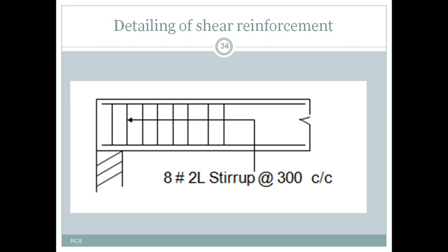We have started the design steps. We have the following design steps. First, we have to calculate the nominal shear stress. Then we have to calculate the maximum shear stress. Then we have to compare tau V and tau C max to check the adequacy. If tau V is greater than tau C max, then only do we have the adequacy for providing shear reinforcement.